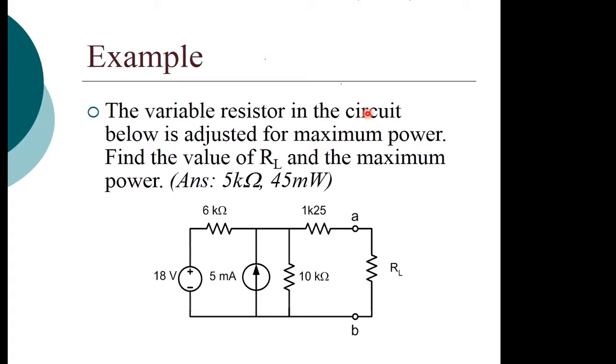Then after that, remember we said Thevenin is the open circuit voltage across terminals A and B. So if it is the voltage across terminals A and B, in the 1.25 kilo ohm resistor the current is 0, so it's out. So the voltage will be the voltage across the 15 over 4 kilo ohm resistor. So our V Thevenin becomes equal to 8 times 15 over 4, and we get our 30 volts.